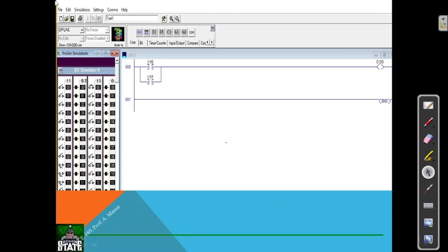Here we will see the OR operation. So what is the OR operation? As we know already, if both inputs are low, the output is also low. If any one of the inputs is high, the output is high. Input 0 0 means output 0. If one input is 0 and one input is 1, the output is 1.